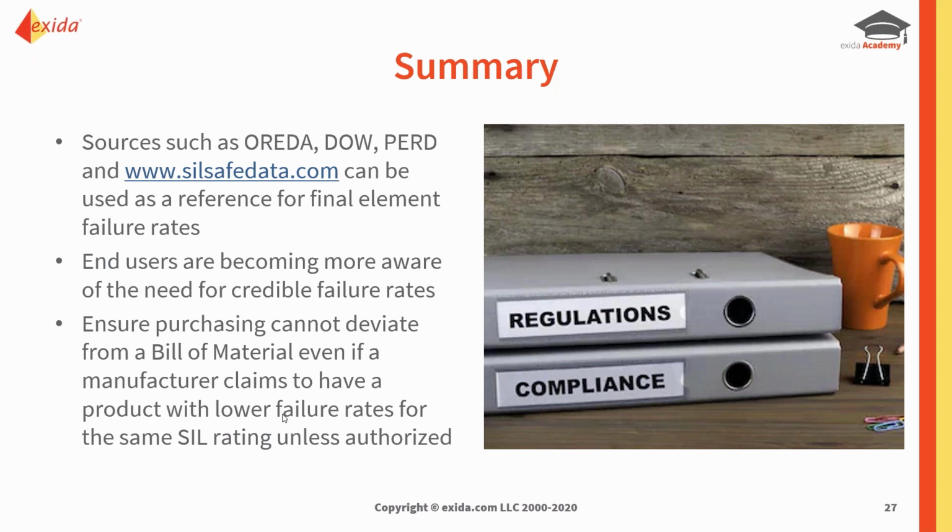The other thing we've come across, and it doesn't happen that often, but it still can happen, and we had it with a client, is that we did a SIL verification for a client based upon a certain valve from a certain manufacturer, and everything passed, and everything was fine. And then 3 months or more later, they came back and said, you know that SIL verification you did for us? I said, yes. They said, well, what happens if we don't use the same valves? And I said, well, it all depends.